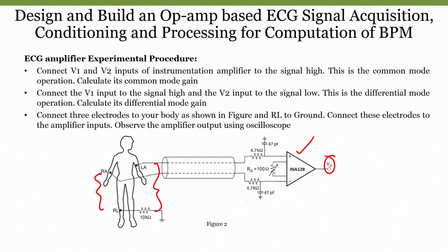But we have also seen that the amplitude of the ECG signals is really poor. That means I also have to set some kind of gain. The data sheet tells us what RG resistance is equivalent to a particular gain. In this case we can use a pot with a value of 100 or 200 ohms. If we feel that a particular resistance gives good enough gain, we can replace the pot with it. Otherwise we keep tuning, and whenever we get a very good amplification factor, we stop. Generally speaking, we will be using a gain of 500 to 1000.